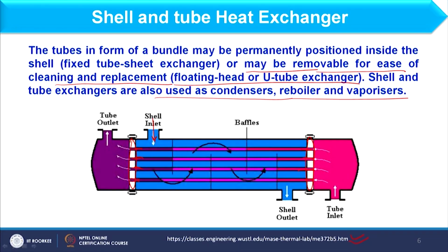Okay, shell inlet is here, exit shell nozzle is here. So, you can see whatever fluid is moving in this shell will not interact with that available in the tube side, because the tube side inlet pipe is there and the outlet nozzle is here. Okay. So, you can see the tube sheet's purpose is to hold the tubes as well as to separate the liquid of shell and tube side.